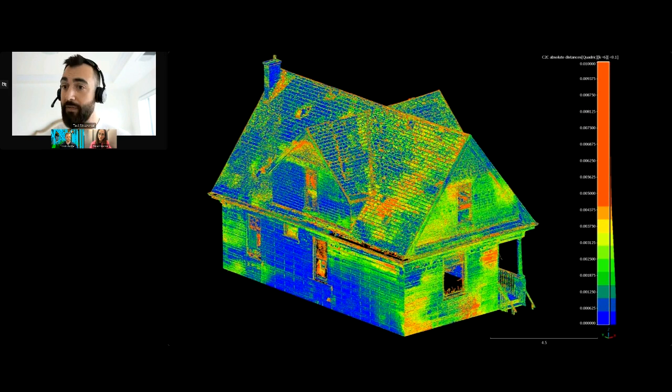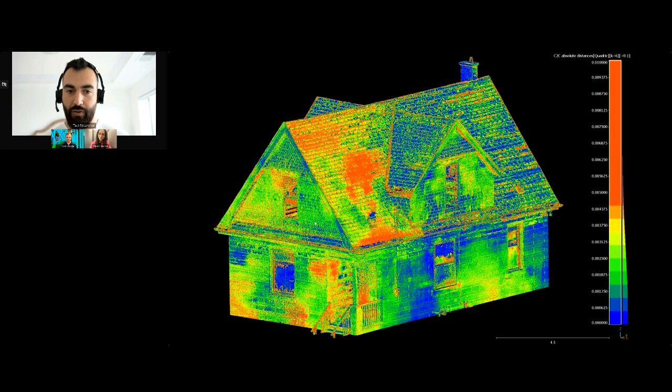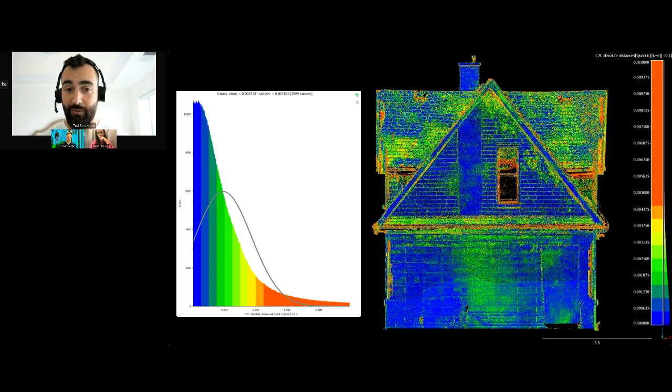There obviously are a lot of outliers here, things like glass and those surfaces that I showed you earlier. I've taken those out of account. I'm looking at anything within a centimeter of each other and how that relates globally to this scan. So you can see very, very close. There are some areas where we're seeing that centimeter distance between the two, and those areas are where you expect them to be. They're on that roof. Remember, there are fewer laser points to compare to there anyway, so it's not directly indicative that there is systematic error or measurement error here, but the distribution is very nice.